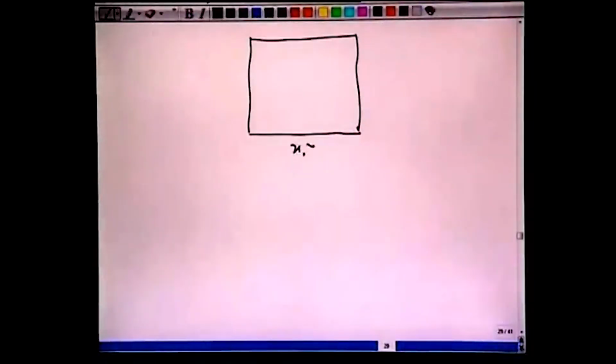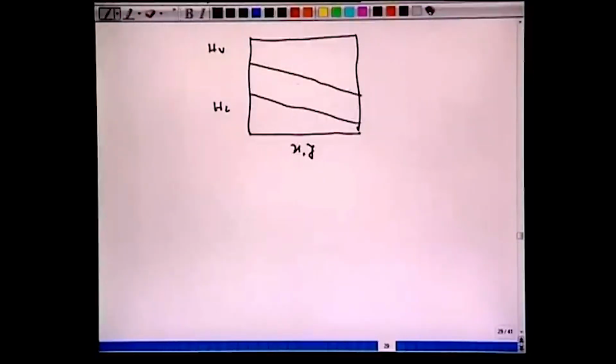So we have X, Y, and if we fix the mole fractions of component A in the vapor and the liquid phase, we can obtain curves like HL, the enthalpy of the saturated liquid, and we can have HV, not necessarily linear or parallel, the enthalpy of the saturated vapors. So if we fix the mole fraction X, then we have HL, and corresponding to this mole fraction we can have this HV.